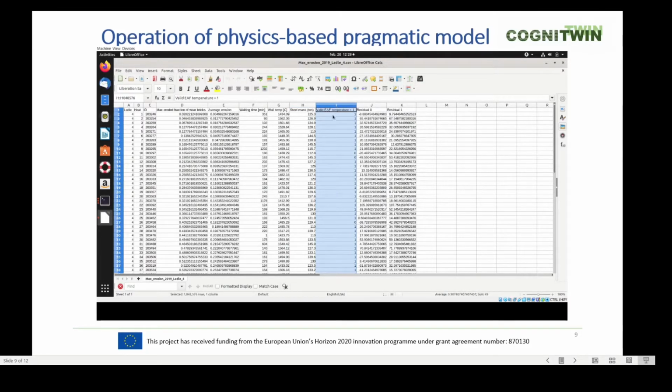In this column we can see if we have temperatures from the electric arc furnace. If we have measured temperatures at this point, we can use this to estimate the first temperature of the steel in the ladle. And this is needed by the model because our model will have to start with some temperature. And now it turns out that the first measured temperature in the operation is actually not a measured temperature. That is a temperature that was sitting in the system from the previous operation in the refining station.